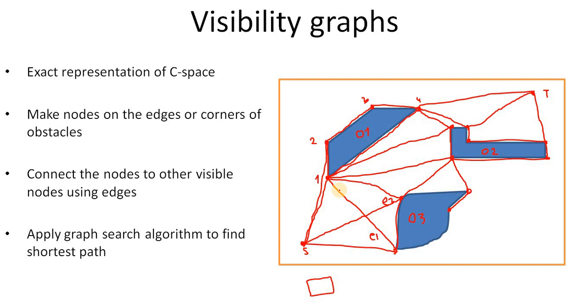So if you want your robot to be bigger in size, then you also have to make the obstacles bigger in proportion to your robot, and then you can treat your robot as a point. For simplification, we haven't done it, or we considered that the obstacles are already inflated. It means when we say that our robot is a point robot, we have already made the obstacles bigger in proportion to the size of the robot.